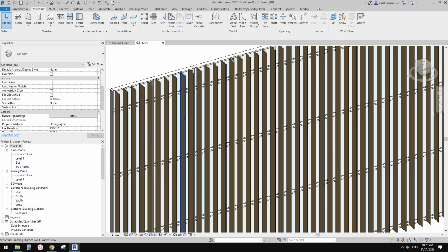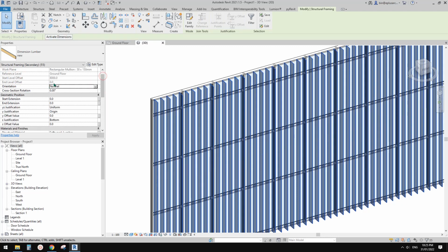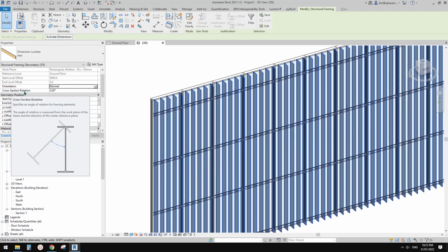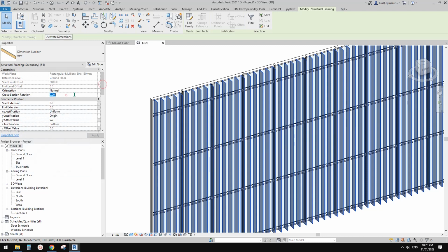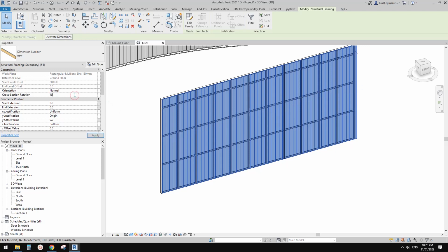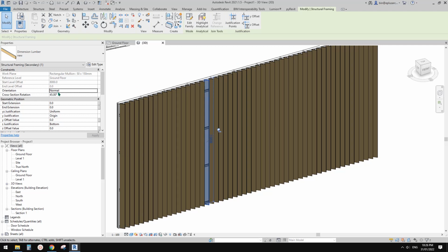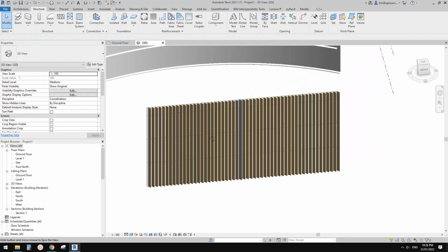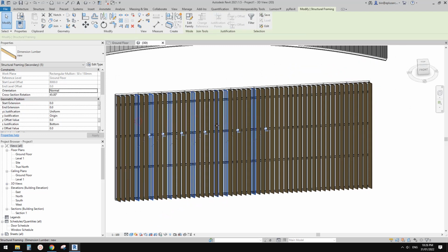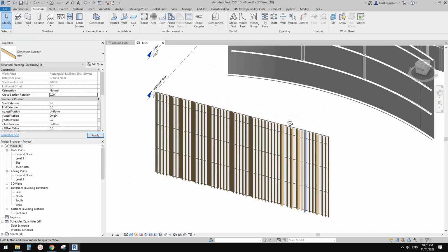And also what you can do is select them, because for structure beam there's a cross section rotation angle. So this one. You can try 30 degrees, 90 degrees, closed, 45 degrees, something like that. And because these are all instance parameters, you can select, for example, this one and make them closed. I want this one to be fully open. So it's very easy, right?